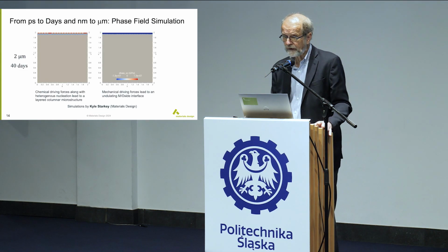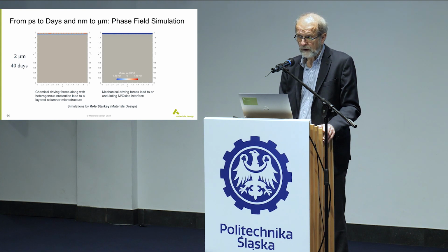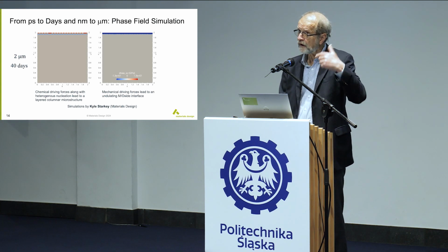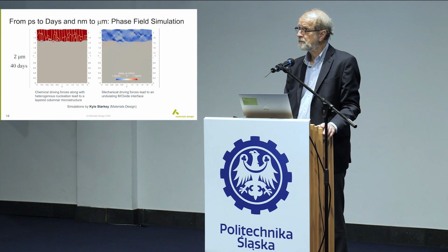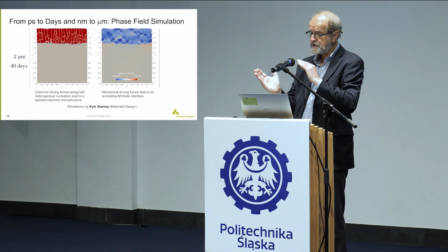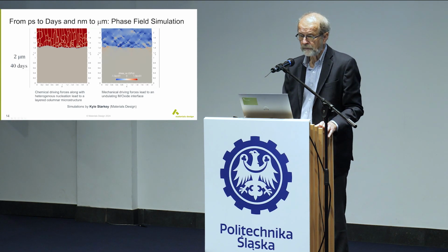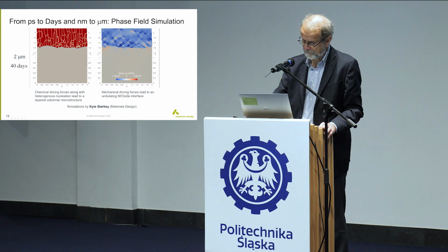So we put it all together and see what we can do here. Now we are looking at a block of zirconium. We are initializing that with some initial oxide grains, supplying oxygen, and putting in all these parameters that were computed, and see what happens. This is the metal part, this is the oxide part, and it grows. That includes the mechanics, the buildup of strain, the orientation, and it has nucleation built in. And what do you see? You see that the interface is starting to get warped. It's corrugated. You do get this columnar grain structure, with a certain aspect ratio.